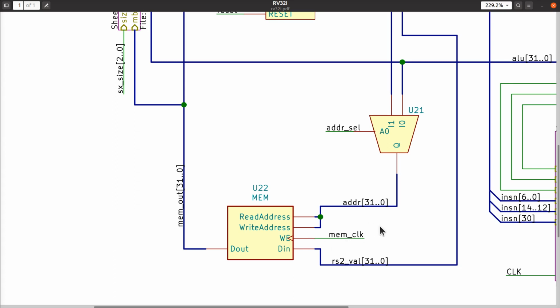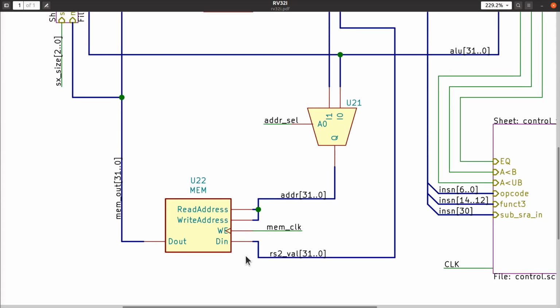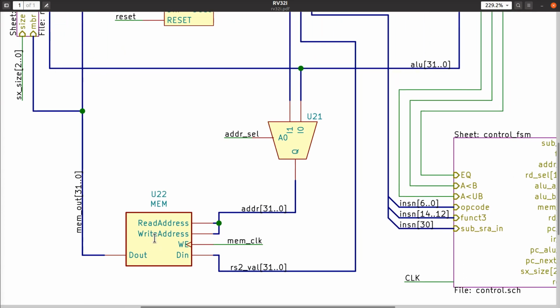Whenever a memory clock has a rising edge on it, it will cause the data that's on this bus to be stored into the memory at the address given in the address bus right here. Again, I'm leaving out a discussion on how memory alignment works and what happens, for example, if I write a byte to an odd numbered address and so on. Surprise, there should be some multiplexers either explicitly in a circuit here or part of this memory block over there in order to align the data to where it belongs in the 32-bit value that gets written into the memory, okay? This is busy enough. I'm going to leave that as a task for the student to ponder and contemplate on their own.